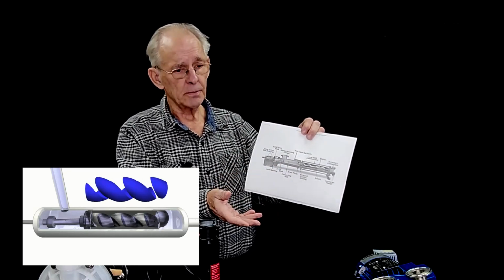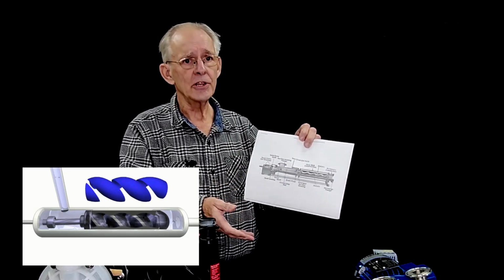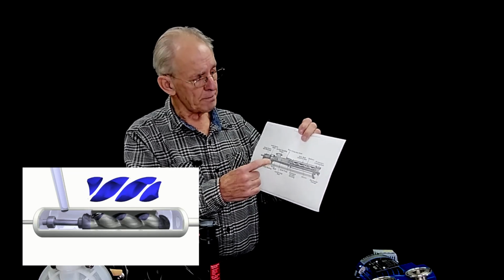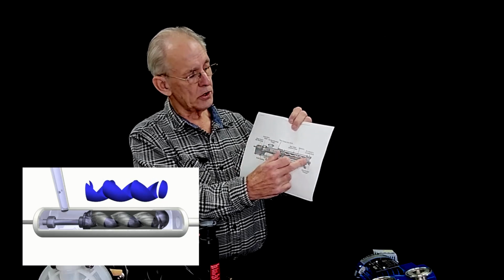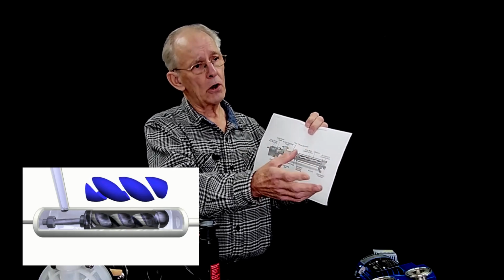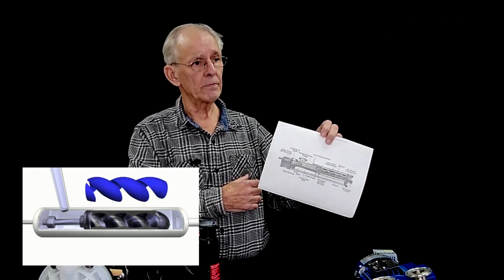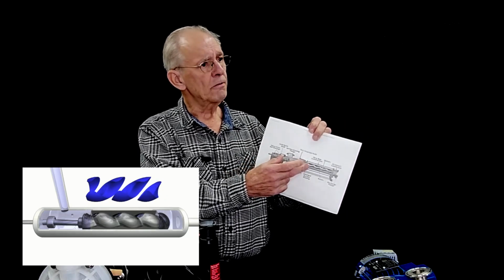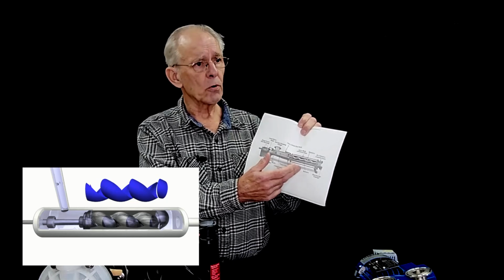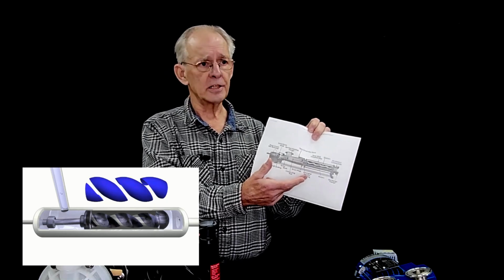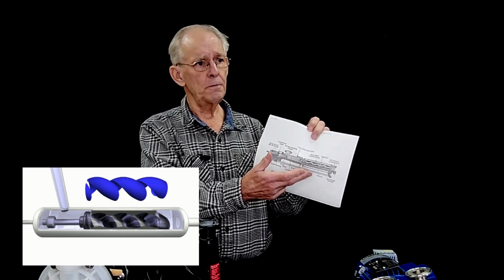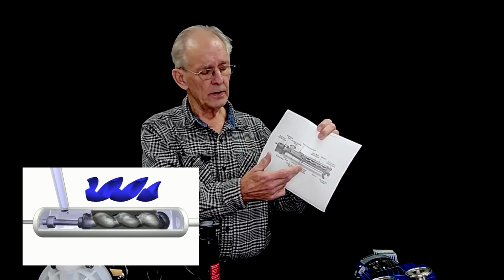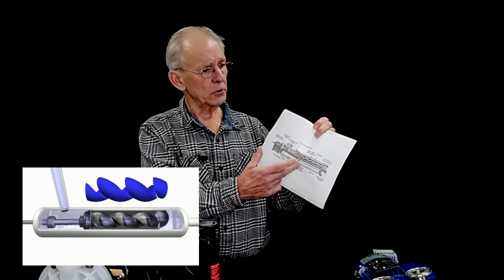Advantage to this pump is it can handle solids, and it can generate very high pressures, and the pressures are based on how long the rotor is. You can put a longer rotor on it, and you can pump as much as 3,000 psi in some cases. These are used to feed things like thick paste. They work really good with high viscosity stuff. They will pump food pastes and things like that, and so that's a real popular type of pump.